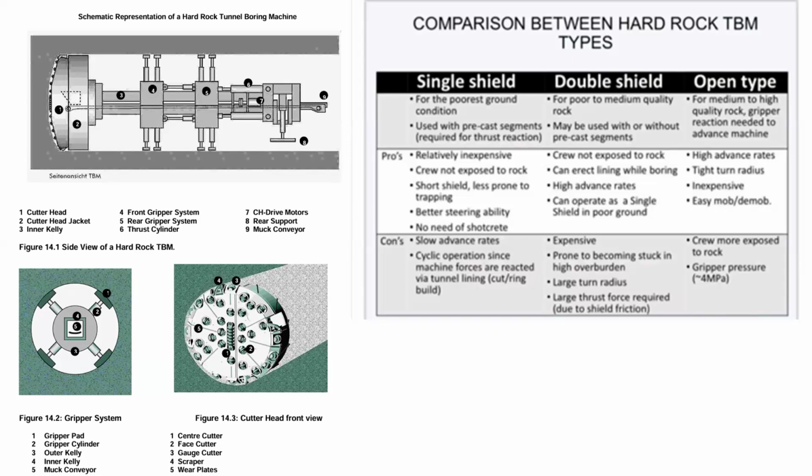And that has happened in Dulhasti project in NHPC. The TBM has been buried inside the Himalayas. Even in Joshimath, there is a hydroelectric project where the TBM got buried and got stuck. And after 3-4 years, they could not extract or retrieve the TBM. So they made an alternative path to avoid the TBM, and then the rest of the tunneling they completed by conventional tunneling.